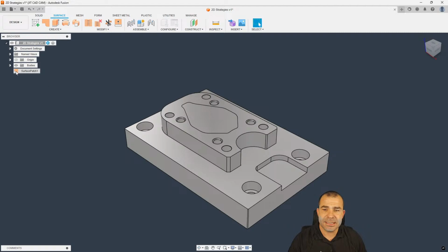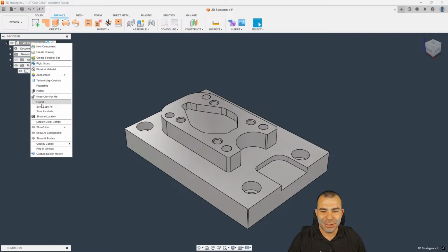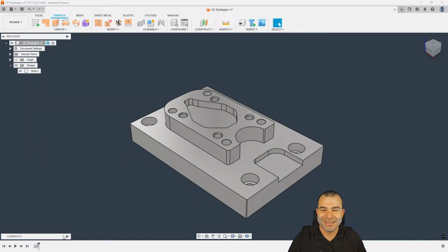And so that you guys can see this on the side, I made the number one rule that you should never do. Let's go ahead and undo this real quick. You should always turn on your design history. So let's make sure we have capture design history on if you're going to be doing things like this. That way you can always go back and undo things. And you'll see here in a minute why that history is so important.